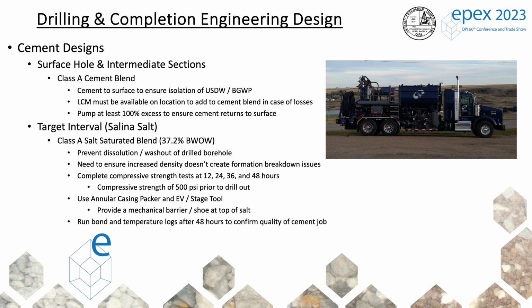For the cement, it's kind of the same principle. For surface, we're just using a regular Class A cement. One thing here, just making sure we're using 100% excess. We need to make sure we get cement returns to surface, protect that groundwater. Then again, in that salt interval, we need to make sure we're using a salt-saturated cement, so we're not washing out during the cement job.